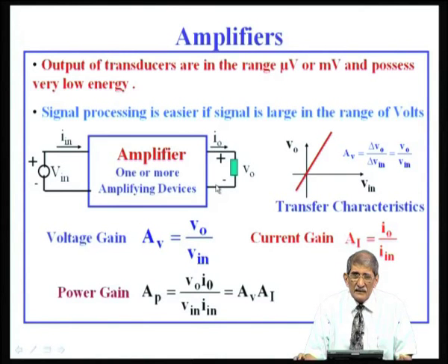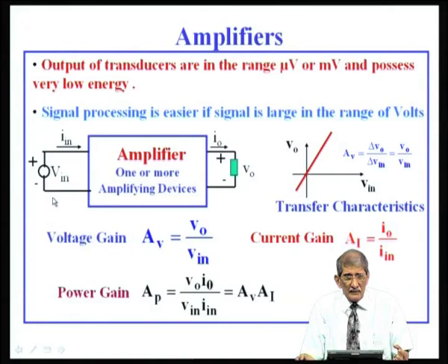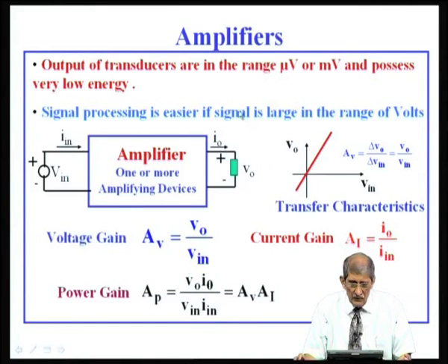Okay. This looks like it is against the law of thermodynamics. If I give input power, how can the power output come out more? The output power has come from the internal circuit. There will be a DC power supply within this amplifier. This may be an AC signal here, an AC signal coming out. I will have a DC bias supply which is used within this amplifier.